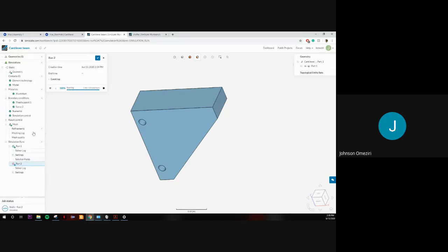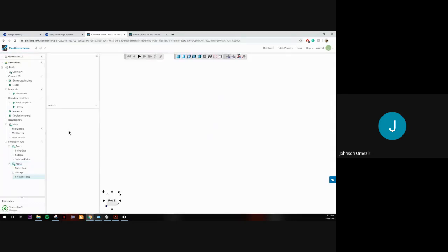That's why, let me even just mention that when you're creating the mesh, the finer mesh you have, the longer it takes to process. So yes, sometimes you might want to show a lot of mesh, but that can also take a while to process. So post-process results, just click on that after the run is done.